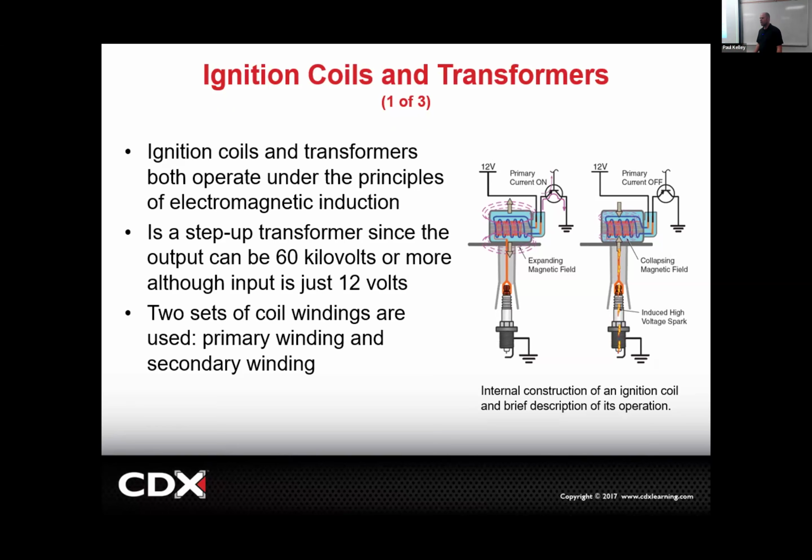You like these sounds. All that comes from air and fuel compressed, and then we have to spark to start the burning, to start the combustion. The spark has to have high voltage. How do we make the high voltage? The coil. The coil is going to take 12 volts in. That's called the primary. It's going to go around a coil so many times, but then the secondary coil is actually going to generate high voltage.